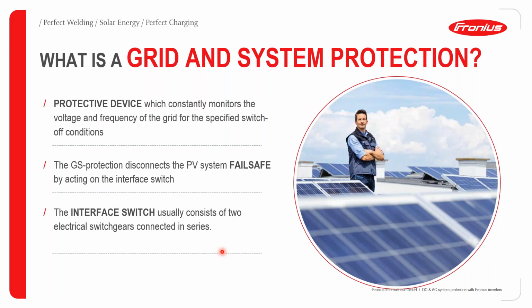It's basically a protective device that constantly monitors the voltage and frequency of the grid at the feeding point for specific switch-off conditions. Once these switch-off conditions are met, the device will definitely activate.